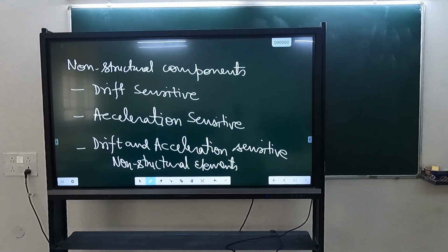Structural performance is covered by inelastic deformation. Okay? So if you have to improve the structural performance, what are we going to do? How can you control deformation in a structure? You know, but how are you going to do that? Well, according to design reinforcement. So how will you design the reinforcement to control the deformation? Like we have deflection limits, we can specify deflection limits.